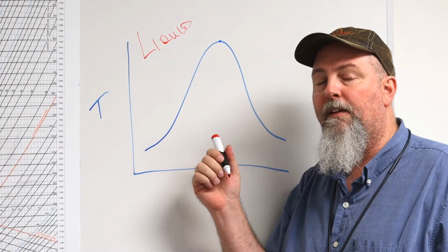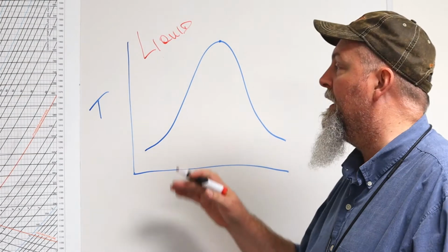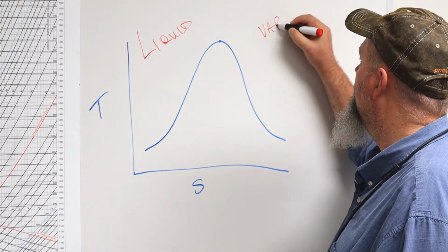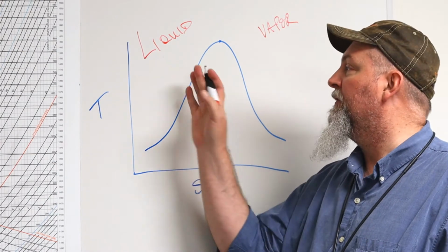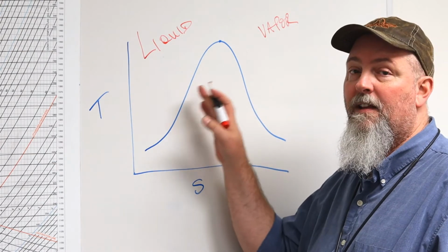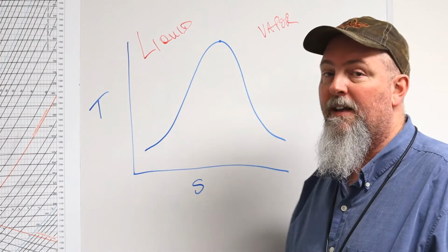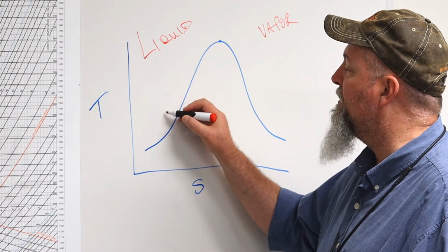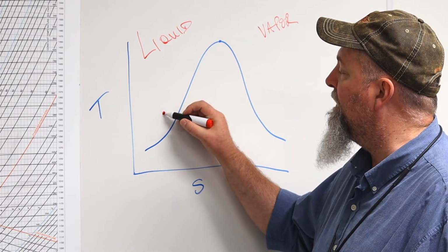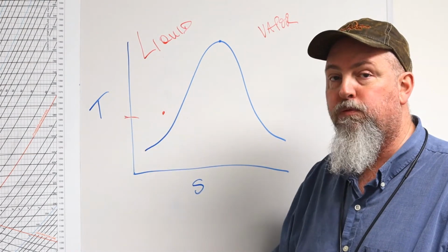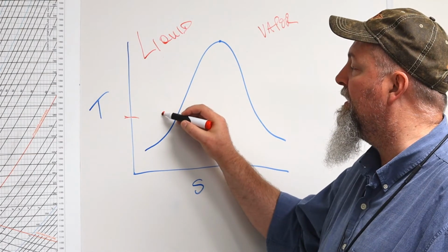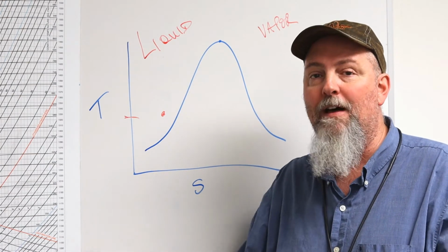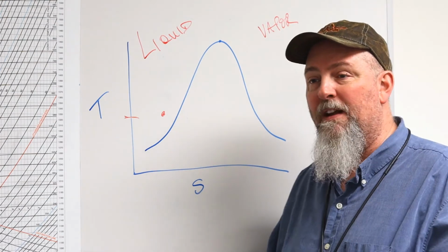And you saw this on that video where Jim and I were talking about it, and he talked through a phase change. And on this side is a vapor. And since we're talking about water, this is steam, and everything inside this curve under this saturation line is some type of steam-water mixture. So if you recall, anything over here, we have a point, and that point is based on some temperature and some pressure. And that temperature and pressure gives that point some unit of energy. It gives it value. It gives it, hey, here's how much work it can do, and here's how much work it can't do.